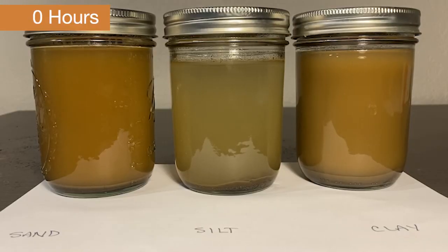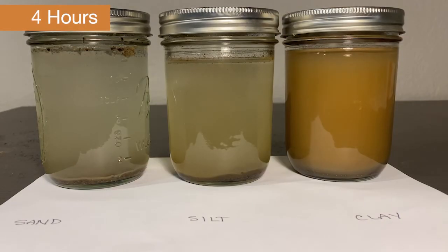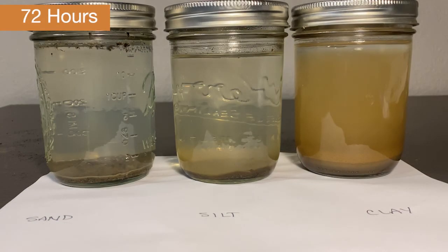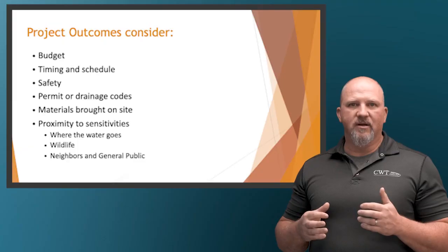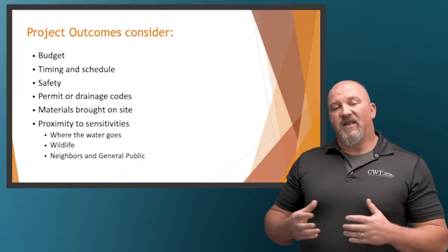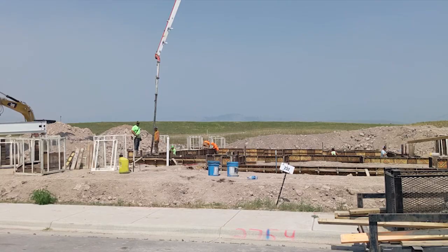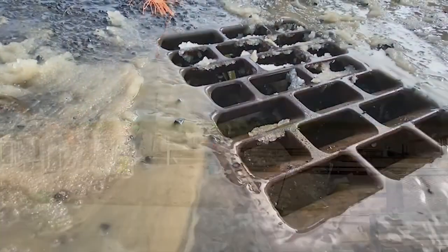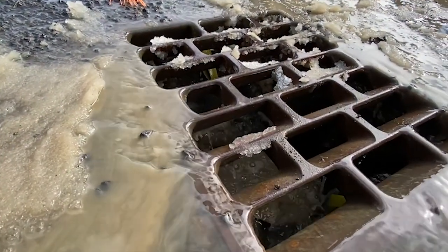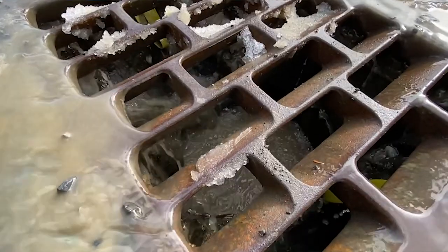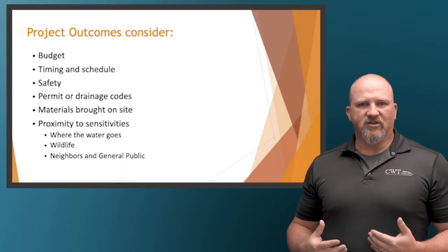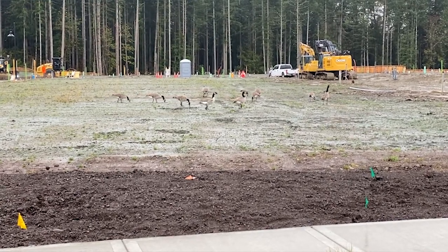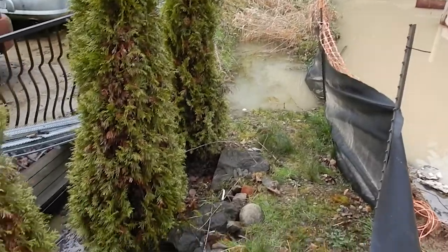The different types of soil that you're working in can greatly influence the erosion and how BMPs are used properly on the project to help particles settle out of the column of water. You need to make sure that there's a time element consideration for your project. Like working in the summer is going to be different than working in the winter from a stormwater and dust control standpoint. And how does that influence your decision making, not only for the project duration, but for your project schedule? And then again, there are these other outside influences like wildlife, neighbor properties, and noise-related issues.